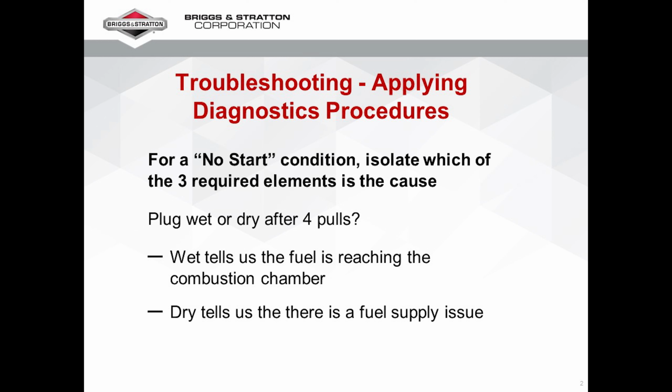If it's wet with fuel, it's highly likely the fuel system is working good enough to at least get a response from the engine. Remember that an engine needs 3 elements to run: air and fuel, spark, and compression. If the fuel is present and it's not stale, one of the other 2 elements is left to check in regards to the no start concern.